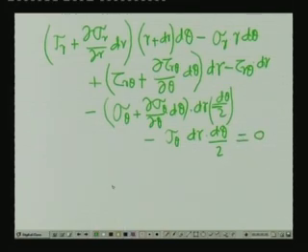Hence, on simplification this gives sigma r times r d theta plus del sigma r del r dr into r d theta. Now, when we multiply with dr, we have plus sigma r dr d theta.